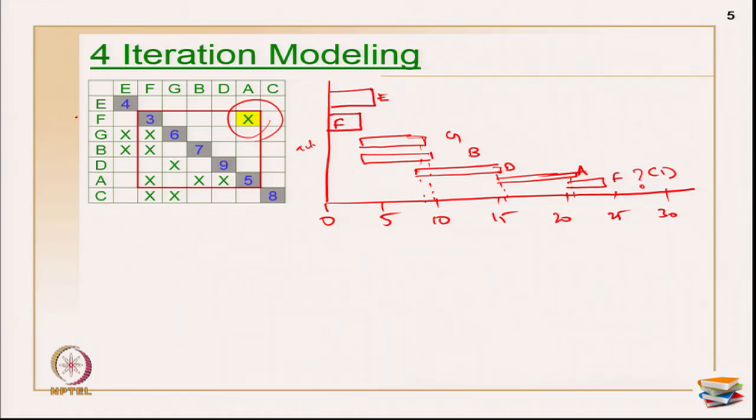Okay, in the repetition cycle, this will be done for 1 day, this will be done for 2 days, this will be done for 2.3 something, this will be done for 3 days, this will be done for 1.67 days, and like that it starts repeating. Okay, and maybe if you want to stop the repetitions in the next round and so on, then primarily that will be after one round of F, G, B, D, A, F, D till A, and then activity C, you will get the duration of the complete project. Okay. So, that is primarily how you evaluate.